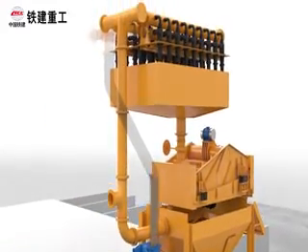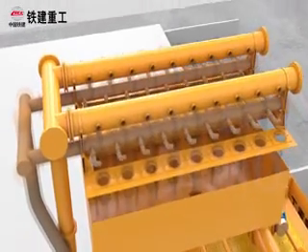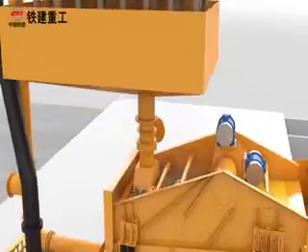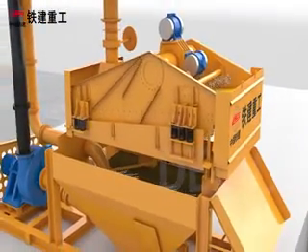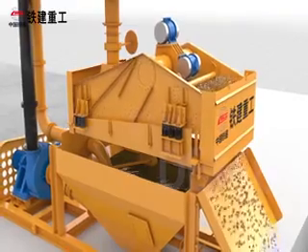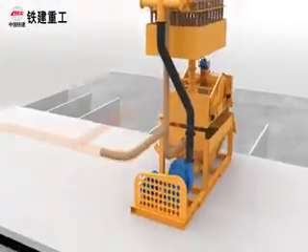Tertiary screening. The pump boosts the slurry in the storage tank C to secondary cyclone module. After the treatment, the underflow slurry enters the lower vibrating screen for dewatering, and particles above 20 micrometers fall into the muck pit for storage. The overflow slurry enters the slurry making equipment.